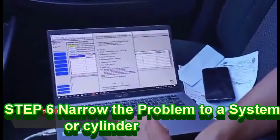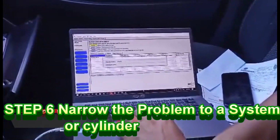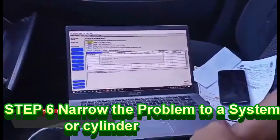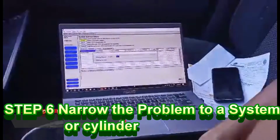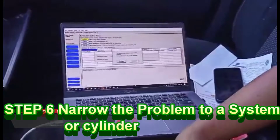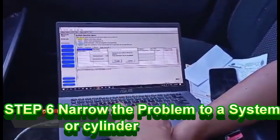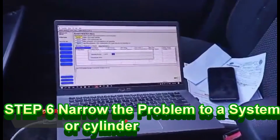Step 6. Narrow the problem to a system or cylinder. Narrowing the focus to a system or individual cylinder is the hardest part of the entire diagnostic process. For example, perform a cylinder power balance test. If a weak cylinder is detected, perform compression and a cylinder leakage test to determine the probable cause.